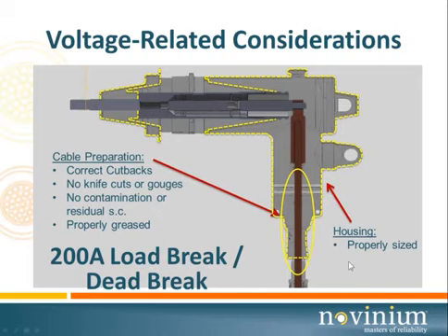That sounds pretty straightforward. You go to the cable manufacturer and you say, I've got number 2, 100% insulation. What's the diameter of my insulation? You get a number. The problem is that's not the minimum number that can be. Both AEIC specifications and ICEA specifications allow that nominal number in cable insulation diameters to vary. You have to know what is the minimum that can be. Are you done at that point? No.